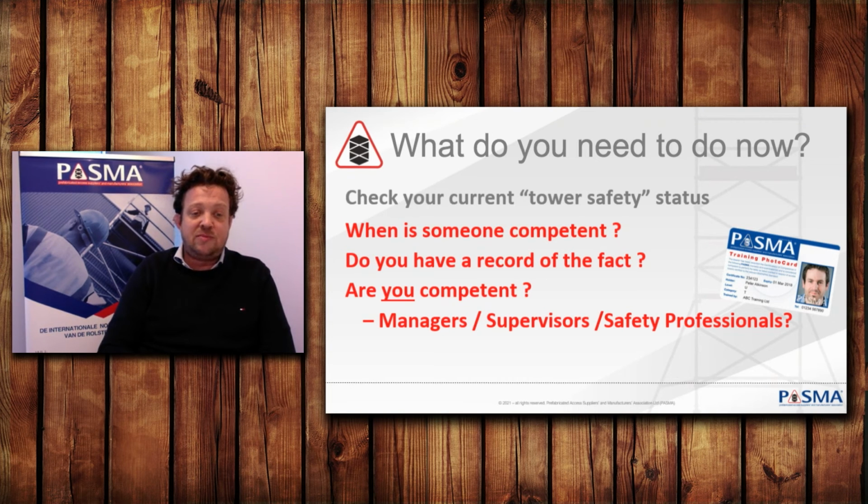What does a competent person at least need to be? Anyone who assembles, inspects, works on or dismantles towers must have up-to-date and adequate training. That applies to each configuration of tower they work with. And if they are building cantilever towers or link towers or whatever configuration, they need to have been trained accordingly.